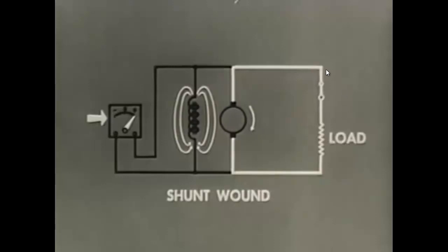So if we were spinning this up, and we had a load on it, then instantly the rotor stopped, we get a linear decrease over time of voltage and current as the magnetic fields themselves decay over time. They would decay slowly because obviously they oppose each other, but the potential over here won't diminish instantly. So there'll be a linear decrease over time.